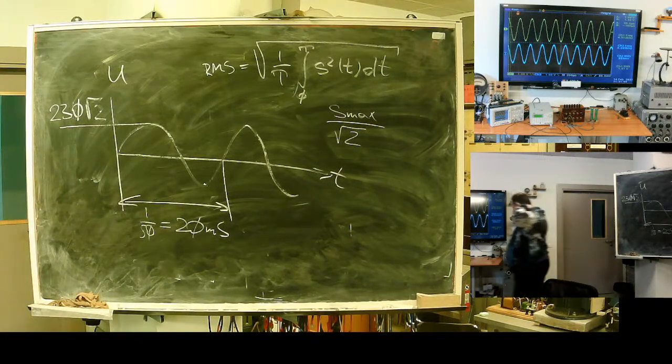That means what? Now it's disconnected. I have a DC network here and an AC network here. This one, 220 volts, if I take a key and switch it on. And here, between the lines, also 220 volts. That means what? Any active resistance connected here will be heated with the same intensity as here. Actual amplitude here is 220 multiplied by square root of 2, 311. Okay, returning back.